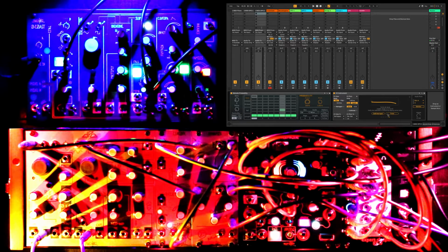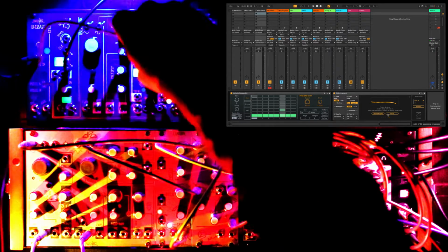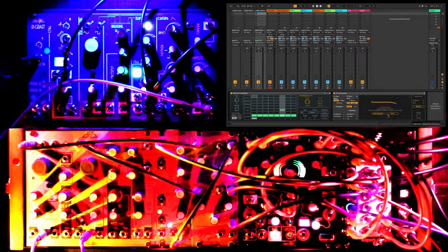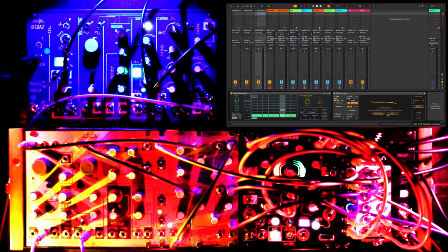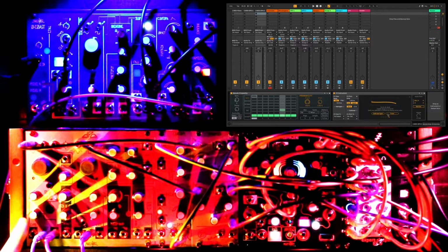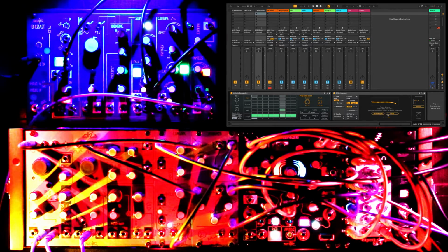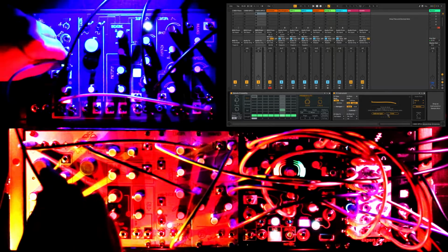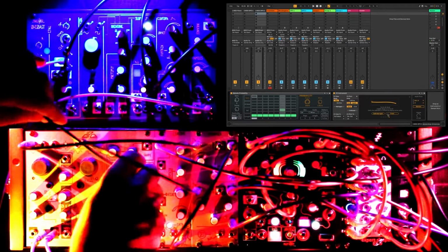Now we're going to make use of the zero coast that's being triggered by the square LFO from CV Tools, and send the zero coast's output to the linear FM input on VCO A of the DPO for some periodic FM bursts to our synth voice. We're also going to patch the stepped random output to the DPO's angle input on VCO B.